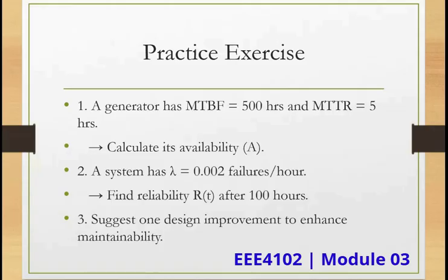And again, it is also good to make sure that you provide clear labeling and access of equipment, or let's say if it is a panel, how do you access it for fast isolation and extraction? That is also critical. And also, as you've seen, the self-diagnostic, being able to add the built-in test, we call it BIT, for speed fault isolation, and easily for you to trace out where the problem is, because it does the diagnosis for you and provides you with that data.